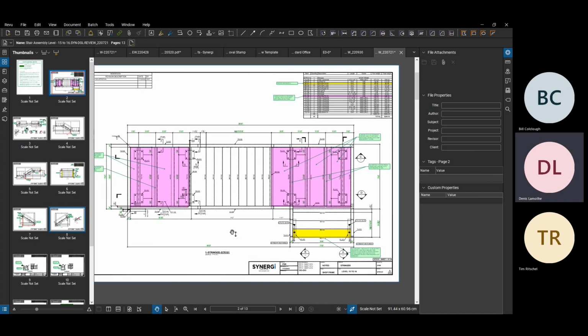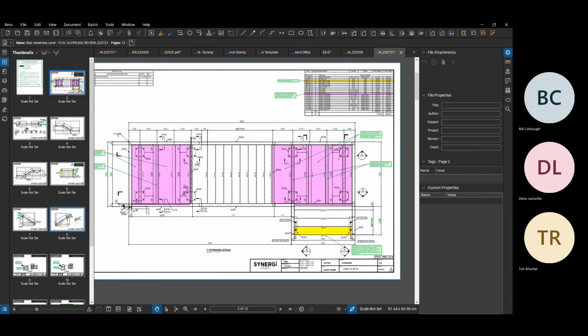Okay. Right. If there is a loose plate, like I said, the mark number for that should go on the erection drawings, so that the installers on site, who may have a copy of the assembly drawings but will primarily work off of the erection drawings, which give them their floor to floors and where the stair is located in plan with grid lines and control lines. So any separate loose parts, any loose anchor bolts, plates or miscellaneous things that are shipped to site separately are generally not included in the assembly drawings. So we check for that.